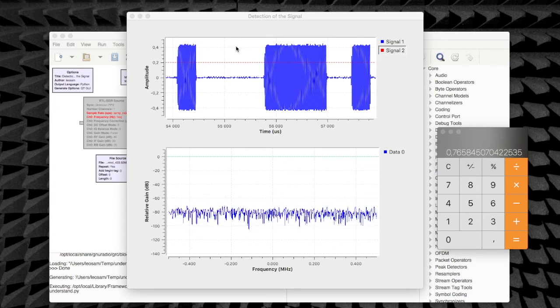Right now, deciding if this is a 0 or if this is a 1 is not going to be very important for us, because whenever we decide that, for example, this is a 0 and this is a 1, then when we start understanding the signal and corresponding that to the information on the remote controls, we can either come back to deciding that this is really a 0 and not a 1, or the other way around. So right now what I'm going to decide is that the 25-75 is a 0 and 75-25 is a 1, but we can always come around and try to change this if this is the case.